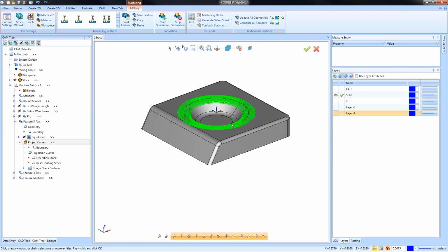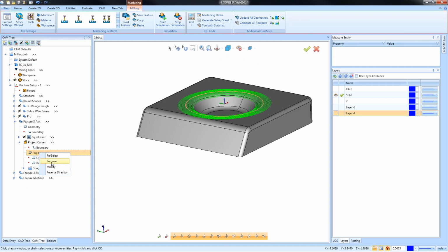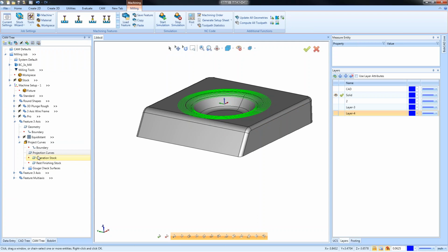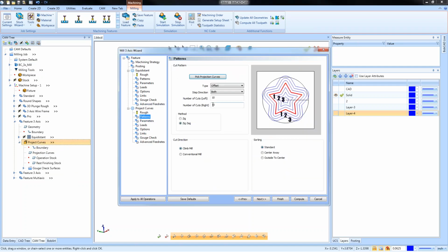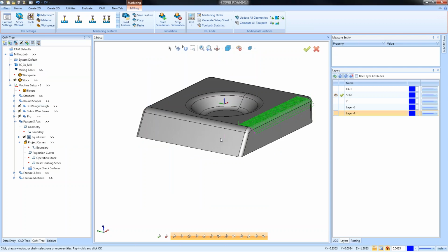There's some limitations. Here I have it offsetting either way, so that looks fine. If I select this edge on the side of the part, let's say like this one here, and we're trying to project down onto that one, we're going to run into a limitation of how far it'll be able to drive that toolpath across a vertical wall. Okay, so if we expand this a little bit more, you can see that it doesn't really cut any further down this way because there's no geometry to drive it. You don't seem to be selecting a surface.